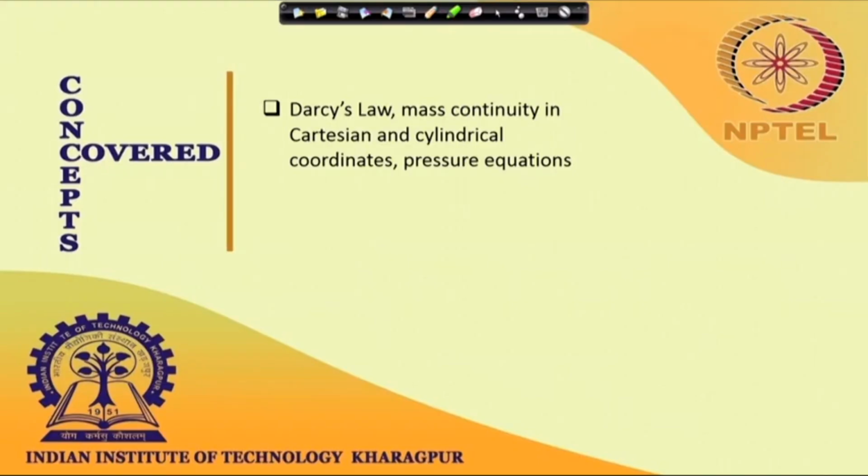What we did next is we extended it to a mass continuity equation in 3 dimensions, and then we extended it to cylindrical coordinates, because in many cases beyond Cartesian coordinates you can leverage the symmetry in cylindrical geometry to simplify equations. So, cylindrical geometry we have considered, and we have arrived at some equation for the pressure profile and velocity. So, let us just recapitulate quickly the equations that we arrived at there. So, we were discussing Darcy's law, mass continuity in Cartesian and cylindrical coordinates, and pressure equations.